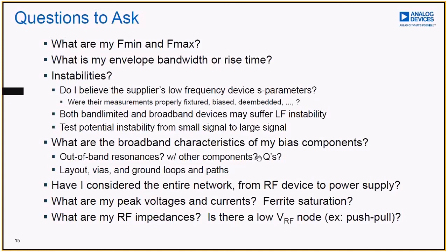We have both RF requirements. We need to make sure that we're not presenting low frequency loads, that we're isolating the power supply at RF frequencies, but we also need to make sure that we're giving the amplifier energy, that we're allowing it to draw current out of the power supply in order to make that RF waveform. So again, these are some things to consider. It's not an exhaustive list, but if you work through these questions, you're probably going to be successful.